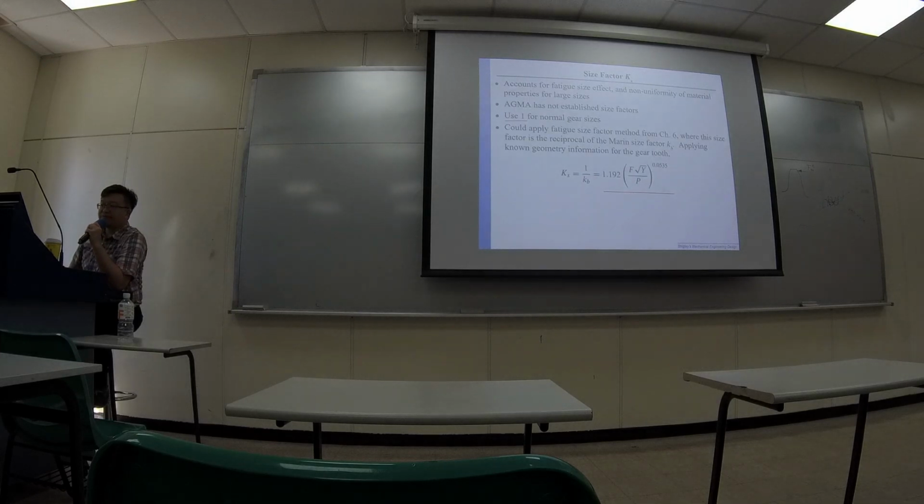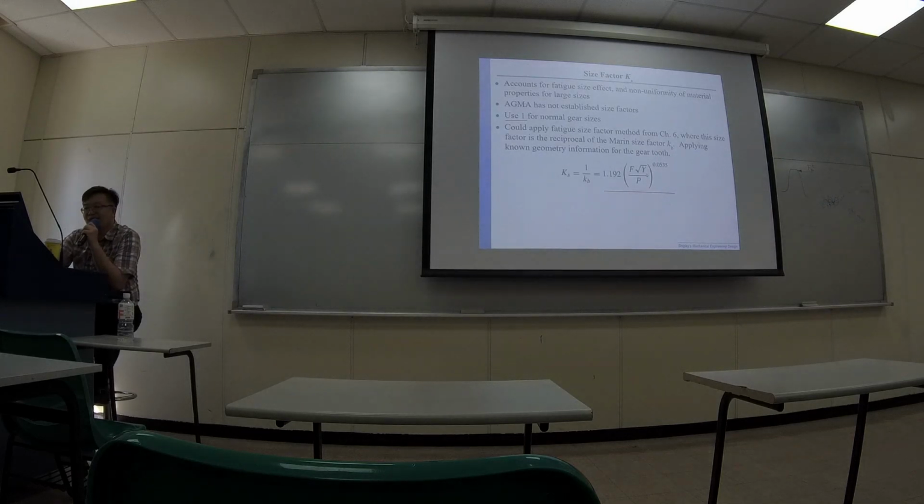Size factor. Based on different sizes, face width, Y, and some other parameters, this is a diametral pitch. Whenever you see an equation like this with some very weird coefficient right here and also in front and also in the power, trust me, it's a model that was built based on experiments.